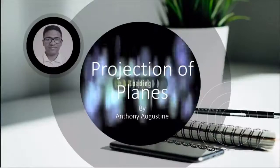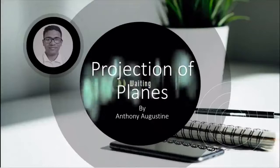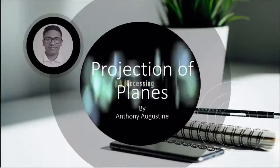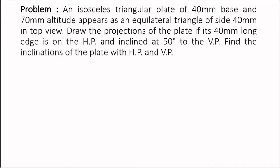In this video, I, Anthony Augustine, would be discussing the problem of an isosceles triangular plate by the auxiliary method. The problem statement says that the isosceles triangle plate of 40 mm base and 70 mm altitude appears as an equilateral triangle of side 40 in top view. We need to draw the projection of the plate if its 40 mm long edge is on the HP and inclined at 50 degrees to the vertical plane. We need to find the inclinations of the plate with HP and VP.